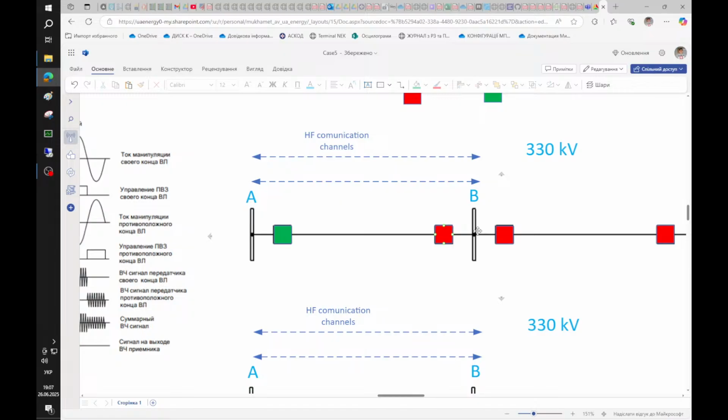It sees these values around 5 to 10 times lower than they should be. So the protection was sent to the factory, and they changed the main board. Now we received this IED back, and it's in work.